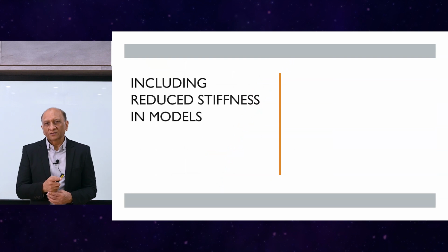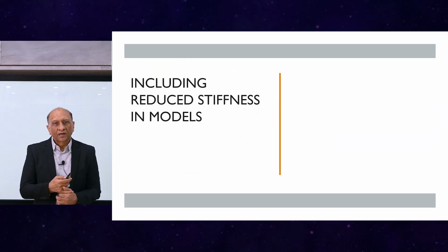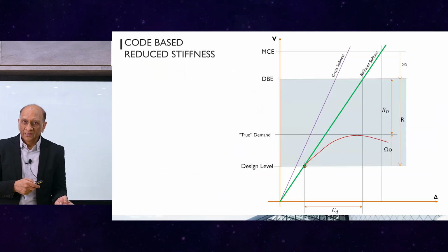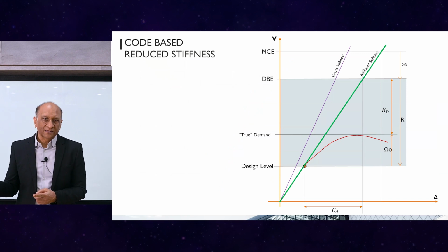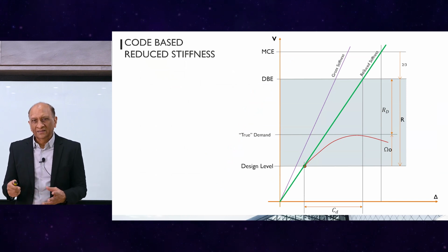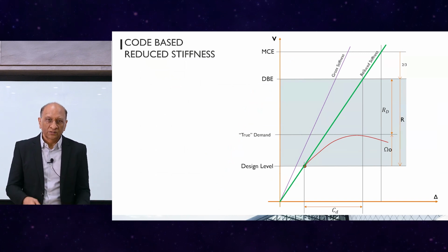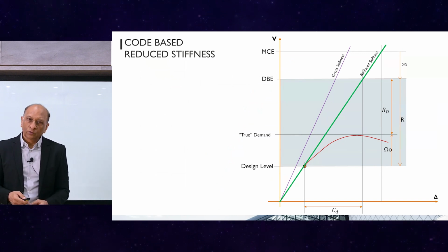Okay, now after we reduce the gross response, you can see here that the natural period has increased from 5 seconds to roughly 7.5 seconds. First mode lengthened significantly from 5 seconds to 7.5 seconds, a 2.5 second lengthening of the period, because the stiffness is reduced in the entire building, especially the core walls.